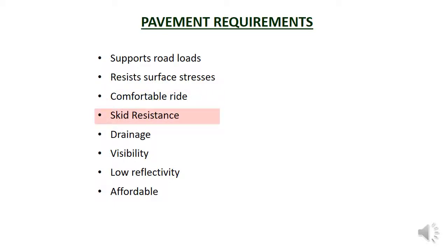The road surface needs to be able to provide skid resistance by having good traction between the vehicles and the road. It is this traction that allows vehicles to stay on the road even when turning corners, during turning, braking and acceleration. Over time, the road surface can be polished by traffic movements, resulting in a loss of traction, so the surface in contact with the vehicles needs to be selected to resist being eroded by repetitive loadings and weathering.